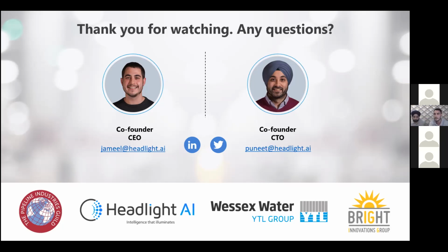But one good thing is that's part of the reason why we included cameras. Using the cameras, especially those side or top cameras, we can sometimes see hairline type of cracks, very, very fine cracks, which obviously sometimes the LiDAR will struggle with picking up. So that's one of the other reasons why we introduced CCTV, the video as well.